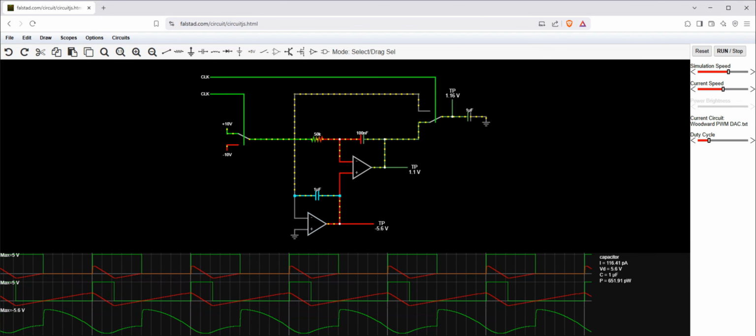Controlling the circuit is, of course, an RP2040. The PWM peripheral is powerful in its simplicity. I can set both the system clock and PWM peripheral clock divider to any arbitrary value, giving me incredible flexibility in timing. Of course, the fractional part of the divider value goes untouched, since I don't want any jitter or timing inaccuracy.